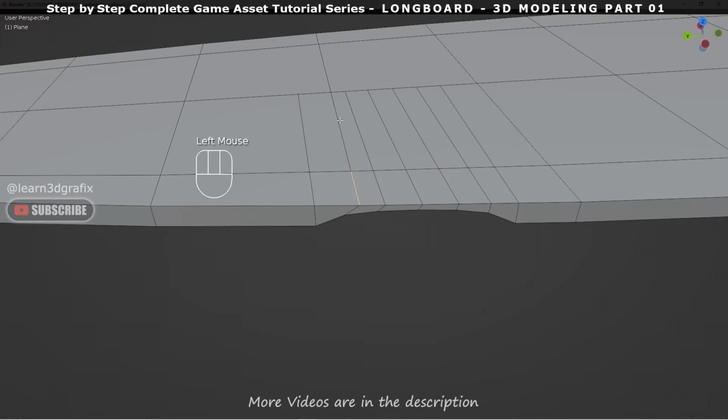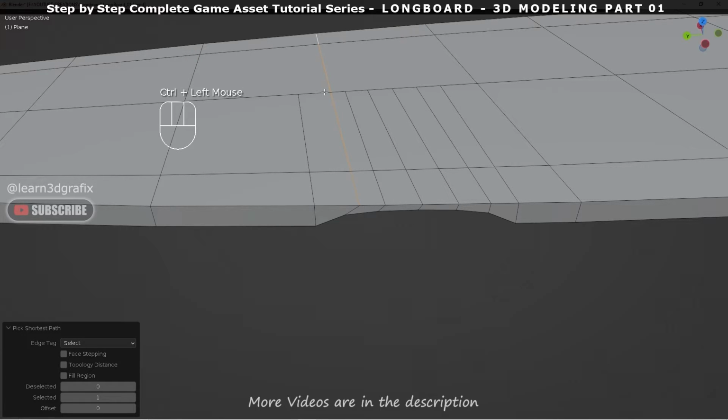Hold down Ctrl and select this edge, and this will select all the edges between them. Now press G twice so that you can move the edges along their normals.